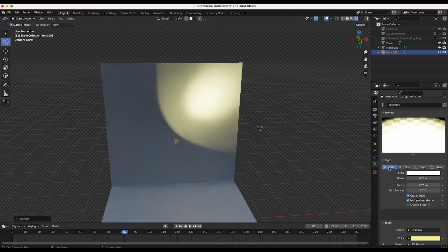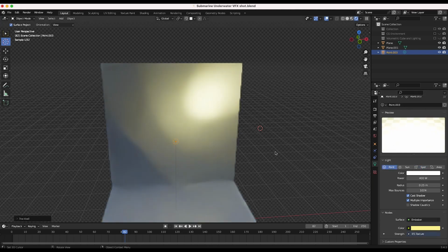We can switch back to our point mode. And now, as you can see here, it's going to be pointing in the same general direction as had we switched it to a spotlight source, but it's going to have that original IES pattern that we have downloaded and put onto this light source.